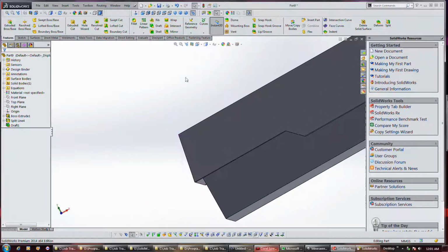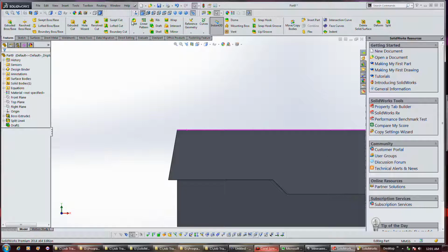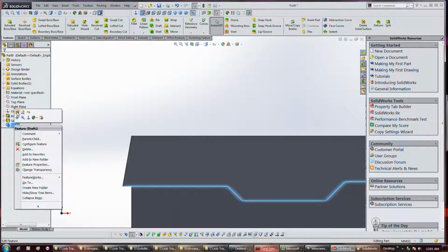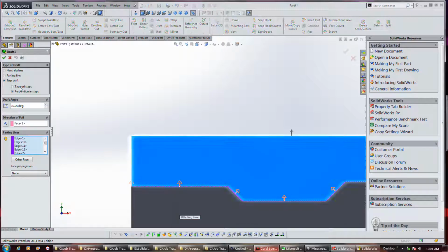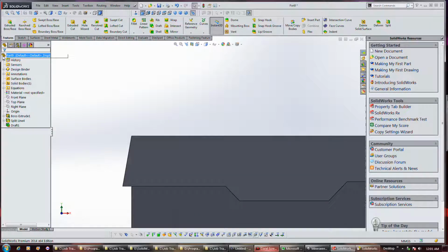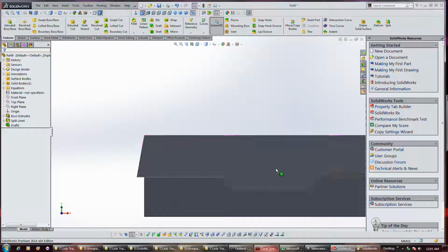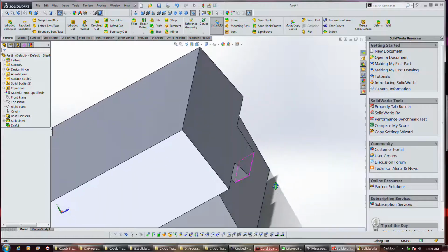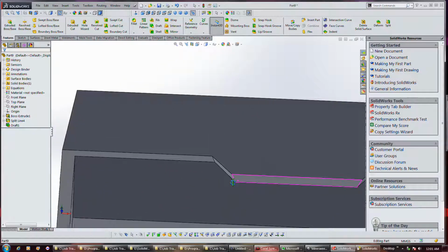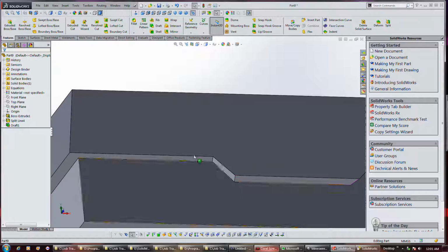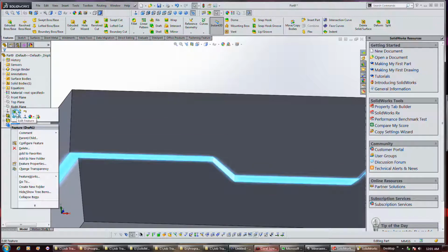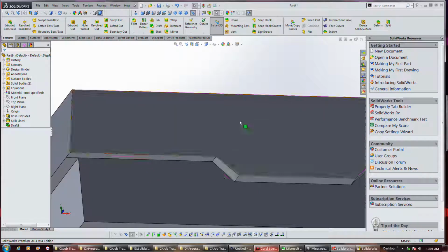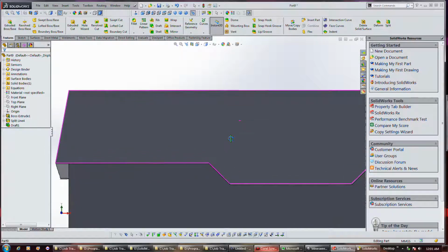Here, you can kind of see, okay, the edge on view, let's see. Okay, well, see the draft angle, there's an overhang here now, because it actually drafted all edges, as opposed to the perpendicular steps, which are just edge on.